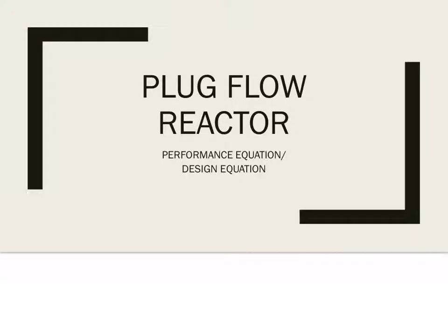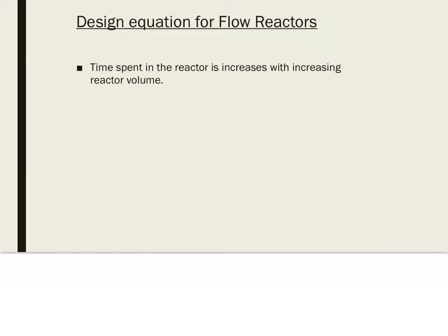Okay, this morning I want to show you how to derive performance equations, or what we call design equations, for another flow reactor, the plug flow reactor, or simply PFR. The design equation for flow reactors depends on the same theory: the more time spent in the reactor increases when we increase the reactor volume.